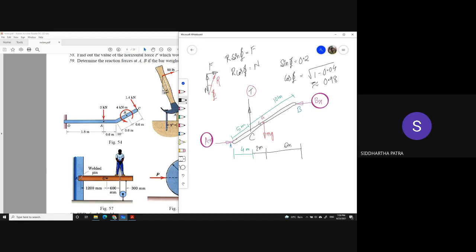Now, this is the free body diagram. Try to get the equivalent force system, and you can actually get the equivalent force system about any point. Let's say some point where you can neglect a couple of forces. The point might also lie outside of the geometry. So you can get the equivalent force system about O. That is also fine.